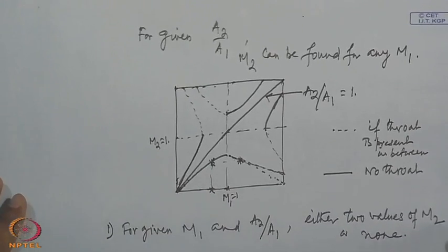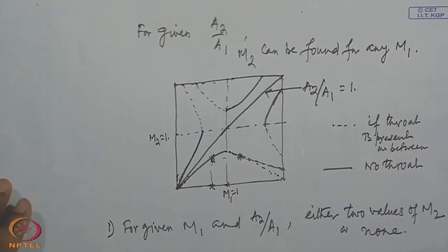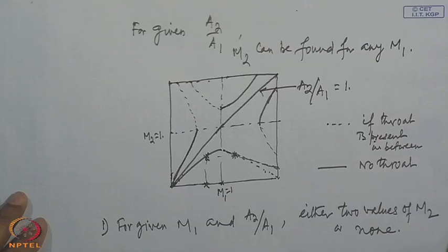However, if the pressure difference across the duct is not sufficient, then the isentropic flow at station 2 is likely to be subsonic. That is, when there is no throat, M 2 can only be subsonic.